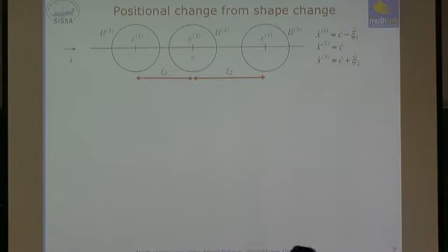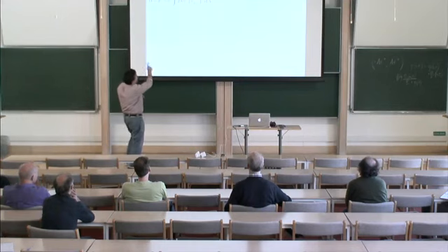Now we have to write down the equation of motion of the fluid, the equation of motion of the swimmer, and combine them. Let's do it. So the essential equation is that the drag, the total viscous force, its component along the axis should vanish. Okay? So F equals 0.